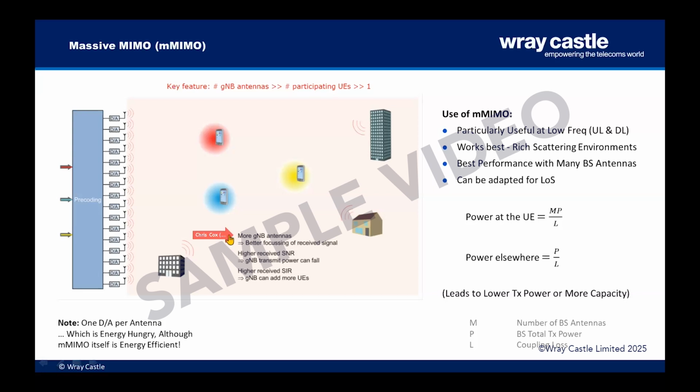The technique works best in a rich multipath environment, loads of reflections off loads of reflectors. In that situation, the mobile is illuminated from all sides, and the received signal ends up as a small patch around the mobile, and most of the energy ends up focused within that small patch, and less energy is wasted elsewhere.